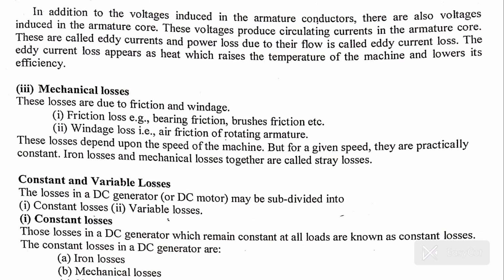Classification based on load. We can also divide all losses into, one, constant losses. These do not depend on load. They remain the same all the time. Examples are iron losses, mechanical losses, and shunt field losses.